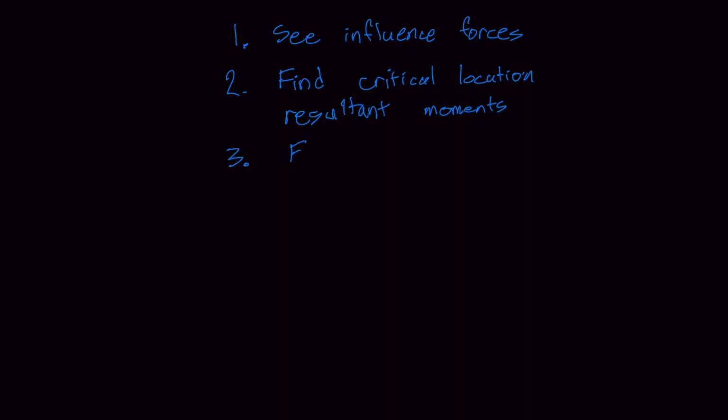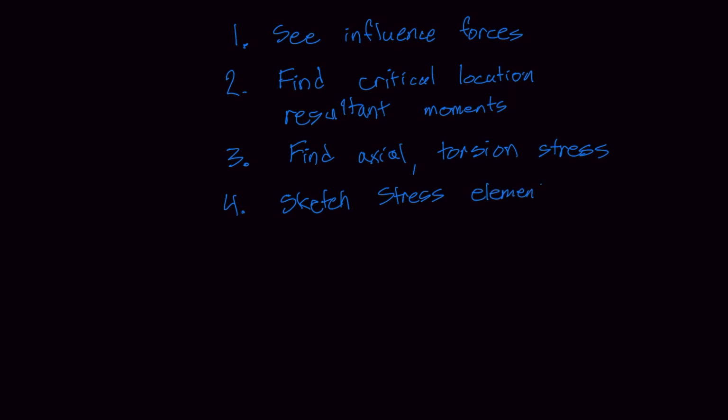Then I find any axial and torsion stress. From there, I can sketch my stress element. Find the principal stresses.